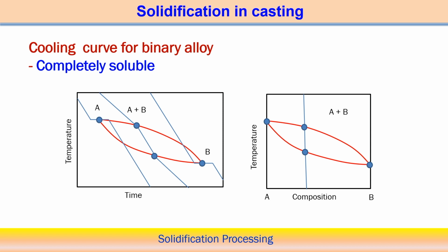So, with reference to this cooling curve, we can try to understand how to look into the cooling curve for the binary alloy, and link it with temperature versus composition in the case of the binary system. Suppose we draw the time versus temperature diagram for different compositions of an alloy. We start with the pure metal. So, a single pure melting point, but over a period of time there is no slope here.